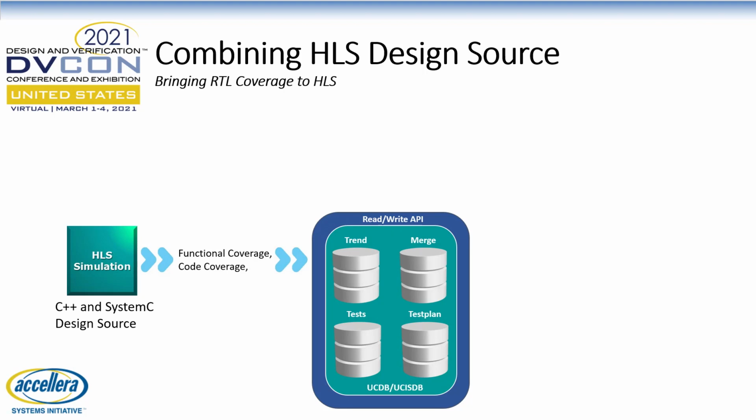Initially, HLS uses pragmas to guide the HLS process, such as the unrolling of loops in HLS design source, which result in multiple unique instances for each iteration of the loop. Catapult coverage is aware of directives such as these, and so it reports coverage for each iteration of an unrolled loop. These approaches result in coverage more closely aligned with the code coverage that will be seen when applying the same tests to post-HLS RTL.